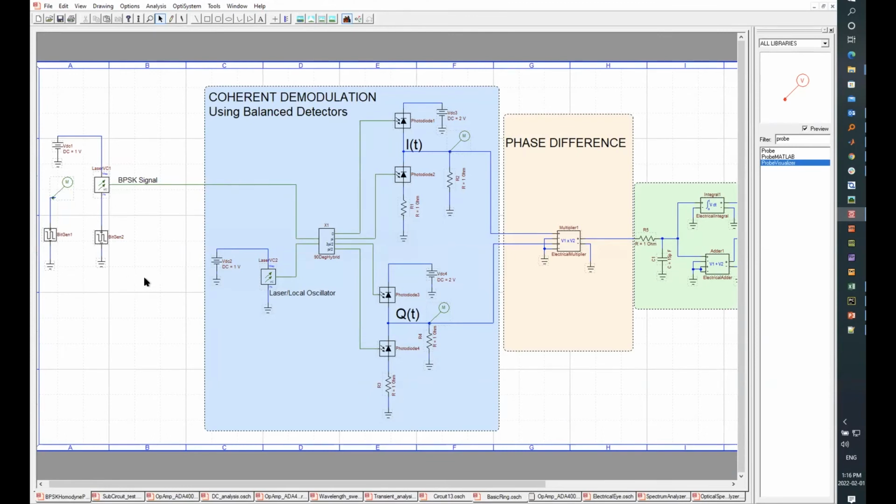The other thing we haven't talked much about before going into the details of this example is that for OptiSPICE, we don't simulate the full carrier. We simulate the envelope of the carrier, but we keep the information of the wavelength in order to make sure that the optical devices behave accordingly. But we are avoiding simulating the optical signal at the terahertz range, specifically because it would force the SPICE engine to take very small time steps to resolve the optical signals. So the signals you have been looking at are envelopes, and we also carry the phase information, so we can handle the correct interference effects for optical signals.